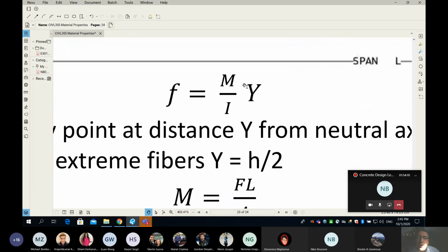Look at this, please. I'll go back to here. We know a few things. Number one, if this value equals F sub R, my beam will fail. And we know if this value is maximum, which is h over 2, this is the fiber that has the highest tension. So very simple. In this equation, you put F equal to F sub R, like 3 MPa, and you put Y equal to h over 2, the height of the beam divided by 2, where you have the highest stress.